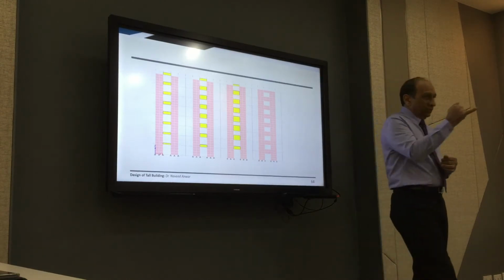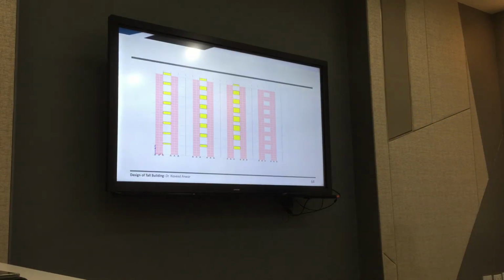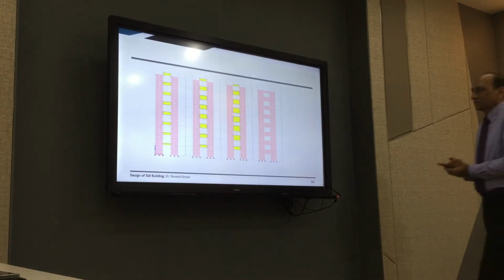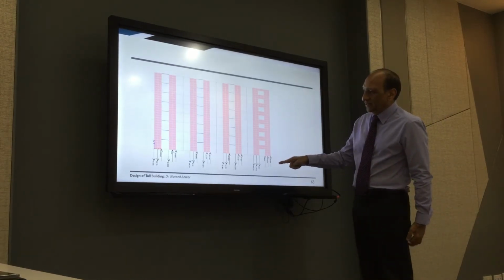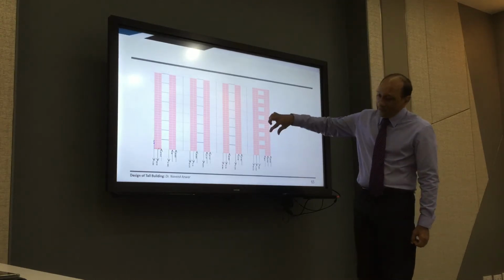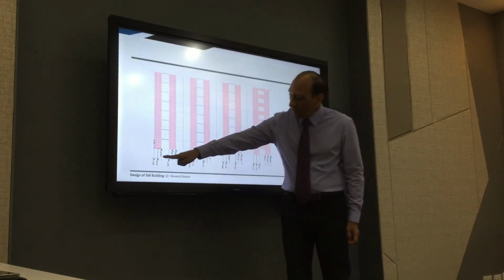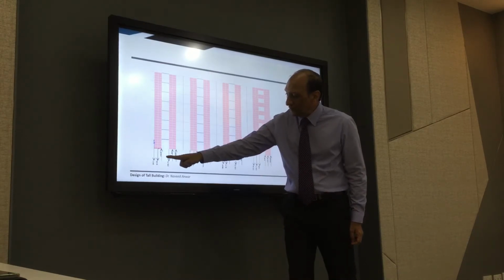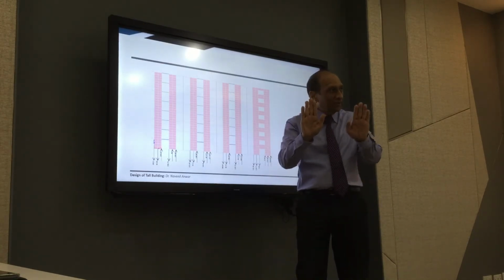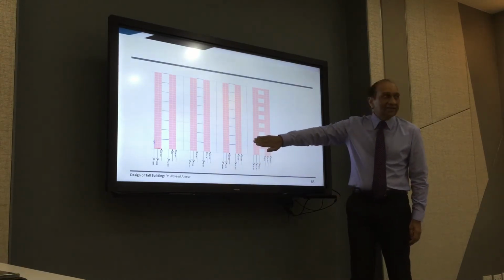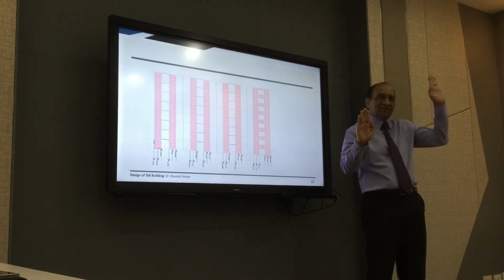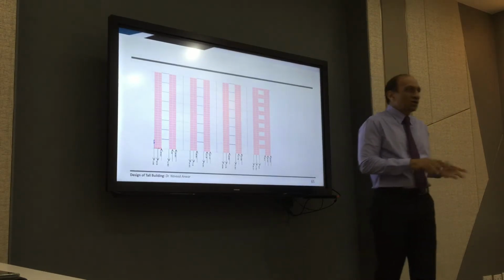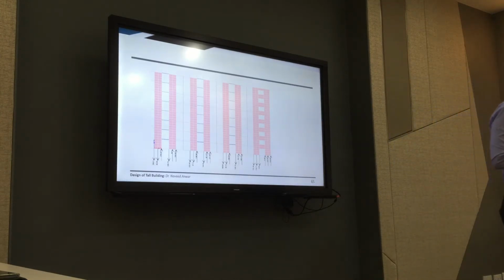So one of your assignments of your project will be to design the link beam. So when you go to the design of the link beam, remember that you design it properly. And you can see the axial forces developing in each case here. Look at this one. Please watch this carefully. Here, each wall has tension and compression components locally. In this case, the entire leg is in tension and the entire leg is in compression. So that means now you have this very efficient system, not local bending anymore. Local bending is completely gone at the base of the wall.